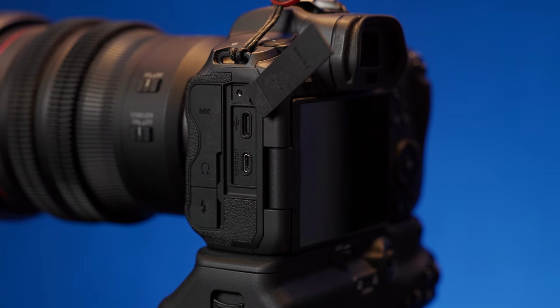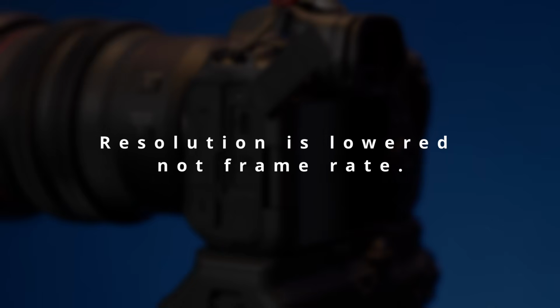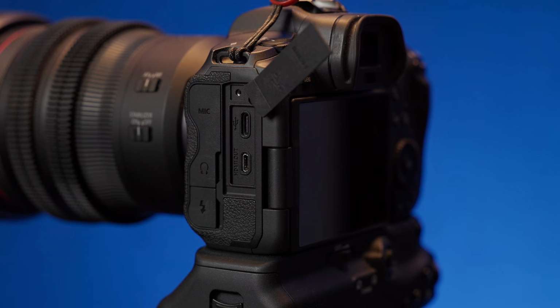Video will still be output when the camera is configured to use a higher frame rate, 120 frames per second, but the output will be limited to 60 frames per second, or 50 frames per second if you're in a PAL region. In the event that your recorder does not support 4K 60, the camera will deliver 1080p 60 instead. In other words, the camera favors frame rate over resolution when your recorder can't deal with the higher frame rate at the higher resolution.